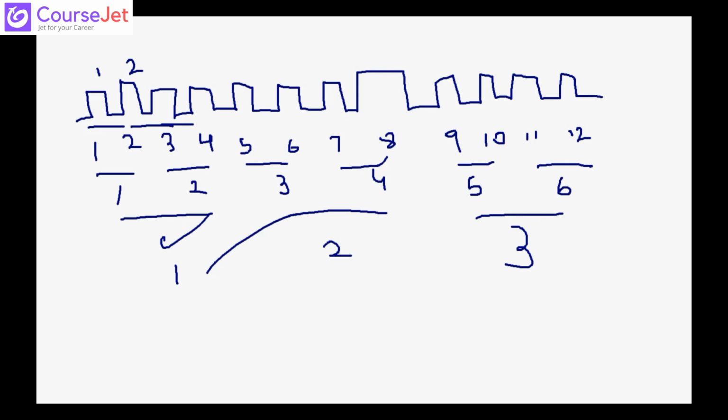Depending on what we take, baud rate will change. We will have to select whether you want to go for 1,200, 2,400, 4,800 or 9,600. That we will be selecting through timer 1. This is already predefined. You cannot use anything else. You have to use timer 1 for this.